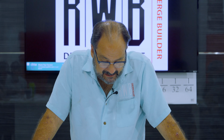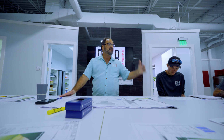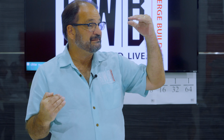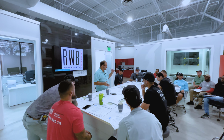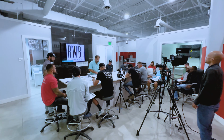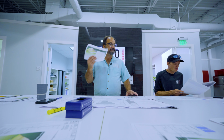What you will find when you look at this is that the neighbor's grades are as important as the grades here. Because if the neighbor's grades are at one height and I cut down to build my house and do my drainage to a lower height, now I have to account for that difference in height. Okay, and we'll get into that when we go to the civil. So let me explain so everybody understands grades. Okay, everybody have this?